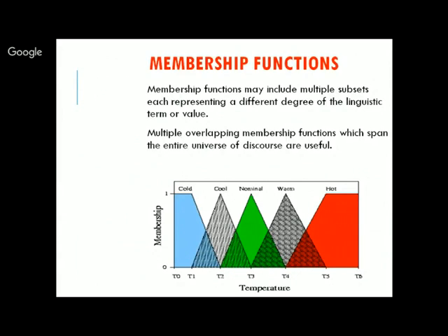Similarly, your input can be speed, voltage or resistance, and your output can be torque. Depending on your control problem, define the inputs and the outputs and specify them in membership functions in graphical form. Defining this in membership function form is known as the fuzzification process. So for any inputs and outputs, you have to first do the fuzzification of it.